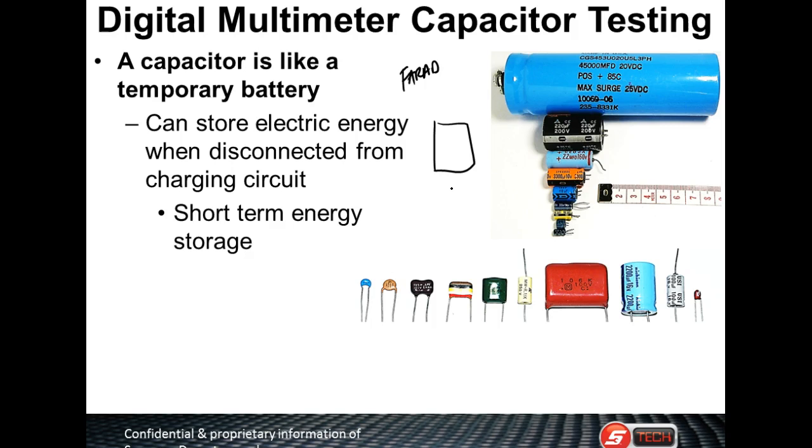But real small capacitors, they have little capacity. They would charge just like that, and we can't check them with a normal ohm meter unless you put a resistor. But these guys right here in DC, we use them as filtering. Their opposition changes with frequency, so we filter out noises that we don't need. We use them even on diodes. If I was to come over here and put this, which is what I'd get off AC, we put a big old capacitor on there, then we'd start moving toward DC because the capacitor would filter out all that garbage. So just about every power supply you're going to see diodes, but then after that you're going to see these big old capacitors in there filtered out.